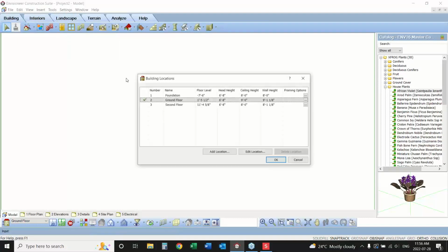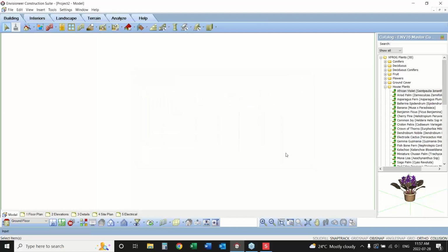I would set up multiple templates if I was you. Get the one created, which got all of your title blocks all created nicely, save it, and then start a new template based on it, and start one with 10-foot walls, and 8-foot walls, and 9-foot walls, or slab on grade. So if you ever get a project that has different heights of walls, it's already set up, waiting for you to go. You just pick that template and go. Okay, so it'll save you time.